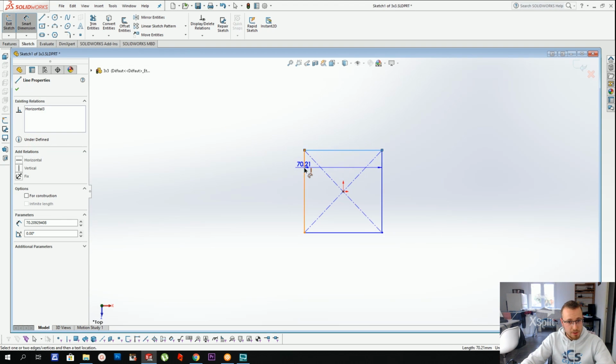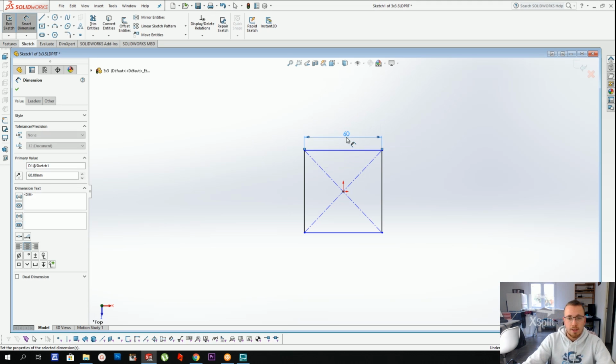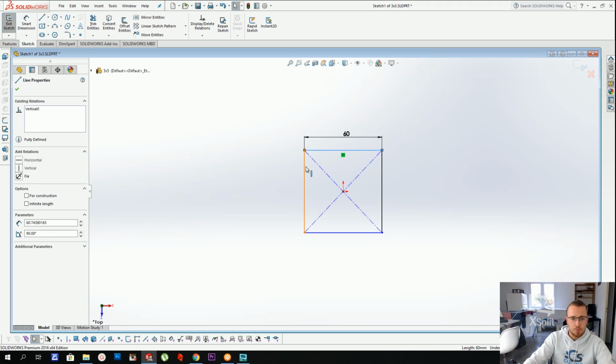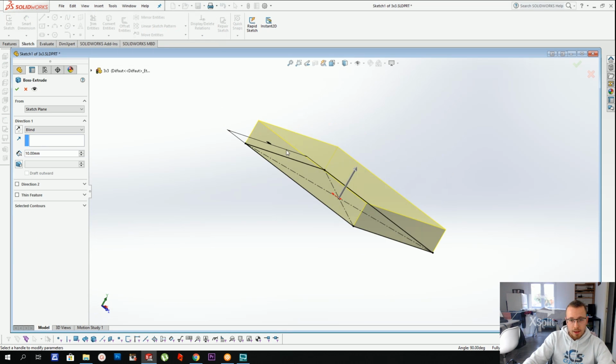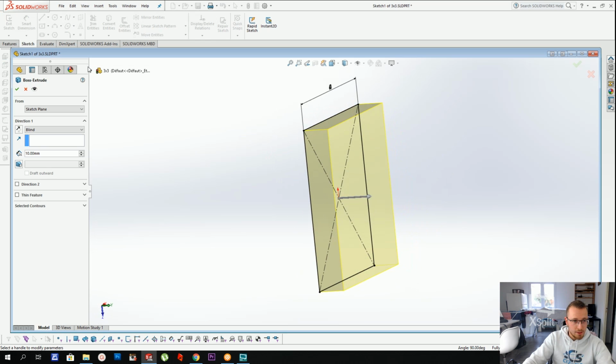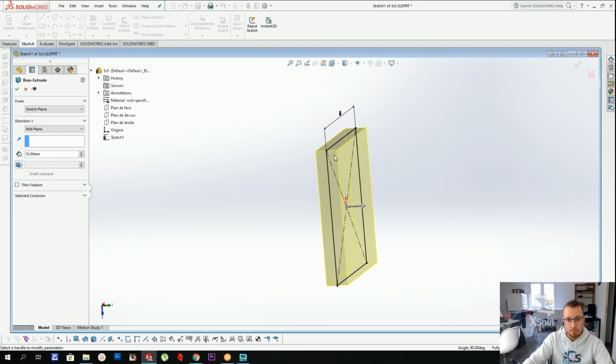So you draw a sketch of a square, and you make sure that all the dimensions are the same, and you actually give it the size that you want. In this case, we're going to go for a 60mm 3x3. That's 6 centimeters to an edge, which is just 3 millimeters more than the classic one. And that way we're going to extend it. And a little tip for you guys, to make sure that the origin is in the center of your sketch, you're going to do something that's called mid-plane, and that's going to extend the sketch in both directions.